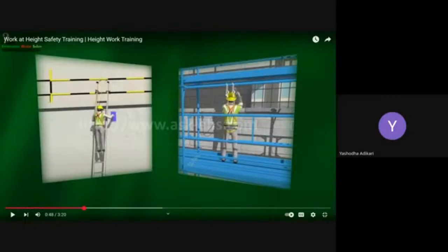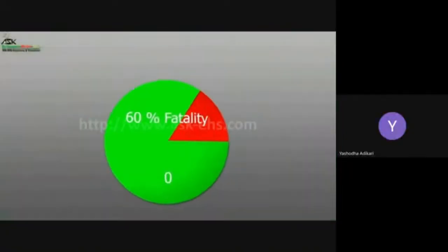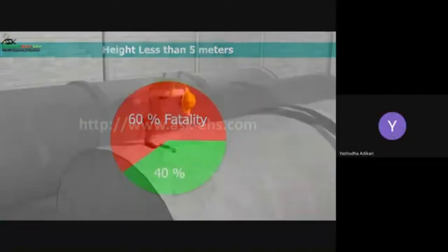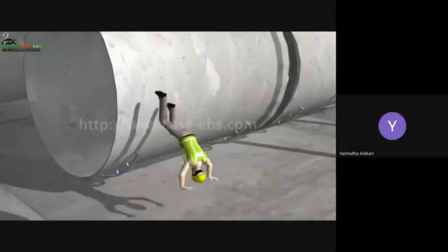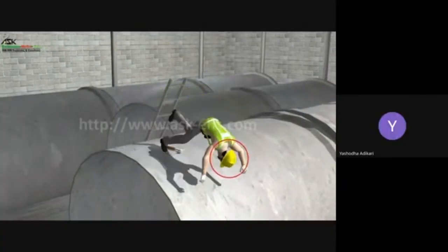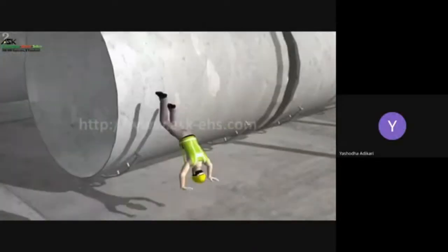Right, so there are some safety belts also to wear before starting your works at high levels. Studies on falls show that 60% of all fatalities occur from heights of less than 5 meters. At heights under 4 meters, people have less time to react. As a general guide, the position you are in at the time you fall will be the position you land in. That is, a forward position can result in landing on your head.